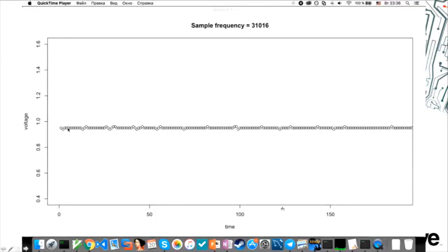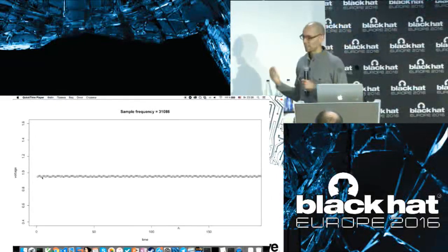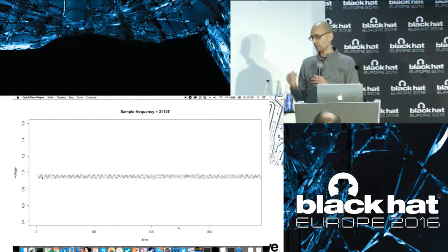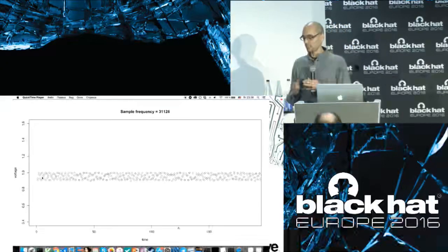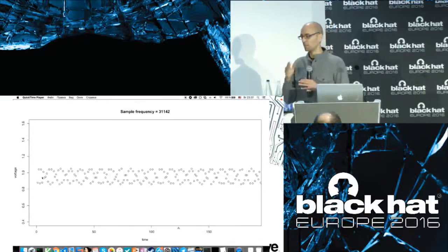And there is also a video here. One thing that happens is that the datasheet says that at this point there should be attenuated noise, right? So maybe it would be okay if we got some noise at that point that is not attenuated, but the thing is that we are getting exactly the same signal that we are putting in the input, but at a different frequency. It's a very weird thing that happens with this ADC. What should happen at these frequencies is that the signal should be completely blocked.